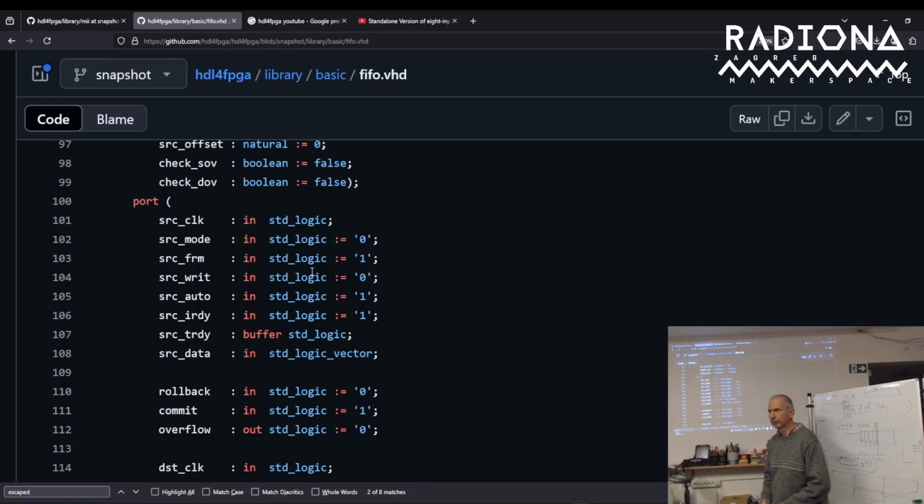Yeah. So in the FPGA, you have, of course, plenty of register units, and they are used to roll back. So they are first loaded to some registers, probably, and there will be just no final write. No, this is a block RAM. It depends on what you want. It could be a block RAM or a distributed RAM. What I do is simply updating the pointers. So when I am rolling back, you just reset the pointer. Exactly.